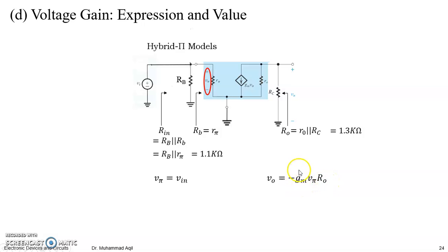So please recall that for the common emitter configuration, you have observed the output voltage by applying an input voltage, right? And you have seen that the output voltage is totally 180 degrees out of phase with the input signal. So your mathematical relation represents this with this minus sign, right? So this is a perfect equation for the output of this transistor, right?